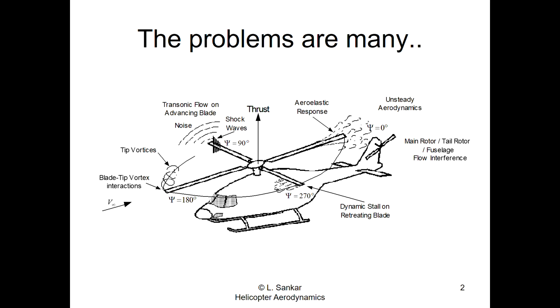At the hub, you have control rods called the pitch links. These are the ones that pitch the blade up and down. So the pitch link is wanting to pitch the blade up on the retreating side, but the nose-down pitching moment caused by the dynamic stall is compressing the blade. So the pitch links see up and down motion, so they go through cyclical fatigue, and they may eventually break. Okay. You may wonder, why can't I make it bigger?